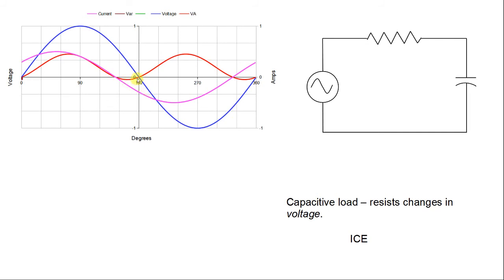And then when they're both negative, it's going to go positive again. And it's back to the point where the amperage goes positive, but my voltage is still negative, that I have my negative volt-ampere waveform, which is some more reactive power that I have in the circuit. So to identify our reactive powers, it is there and there.